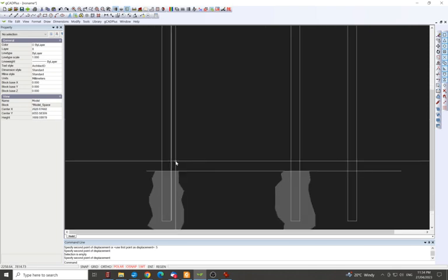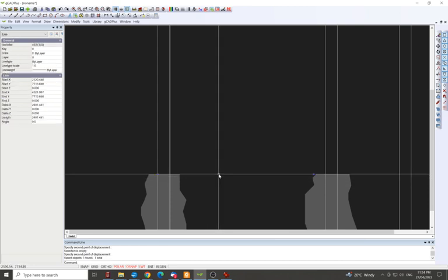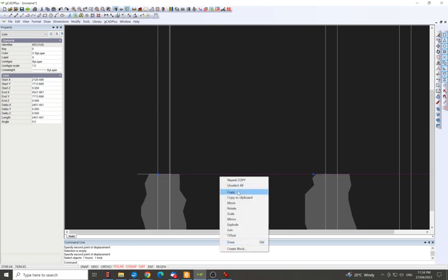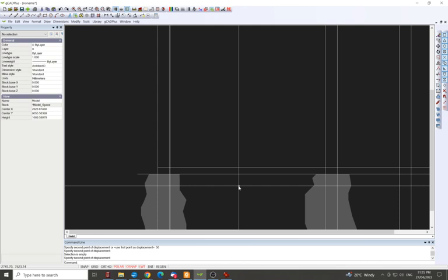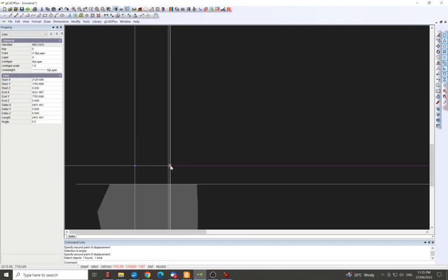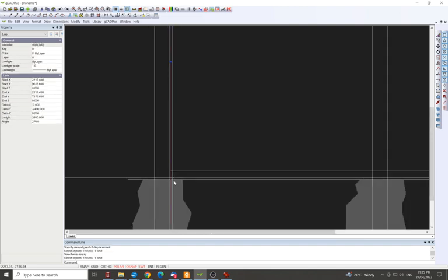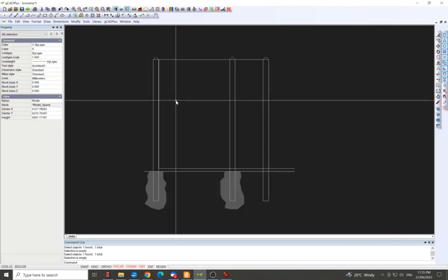Now it's at 2400. We don't want it at 2400, and we want the gate frame to be about 50mm off the ground. So we'll get this bottom level here, copy that, and move that up 50mm too. And then we'll just use these other references. You're always working off our previous reference, our ground height or post height, and then we'll just move those back to that one. Snap that onto the corner, and you'll see how this frame starts to come together.